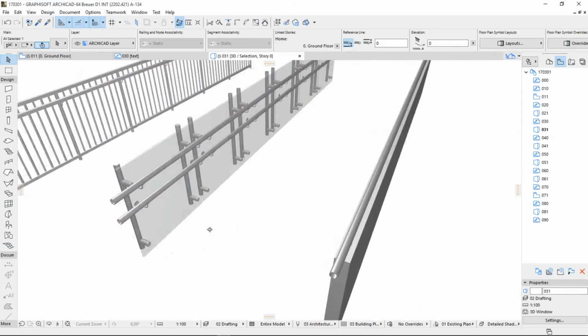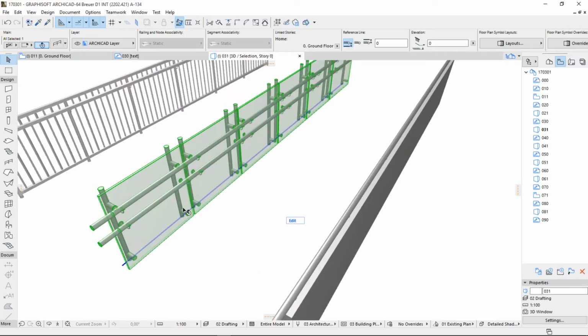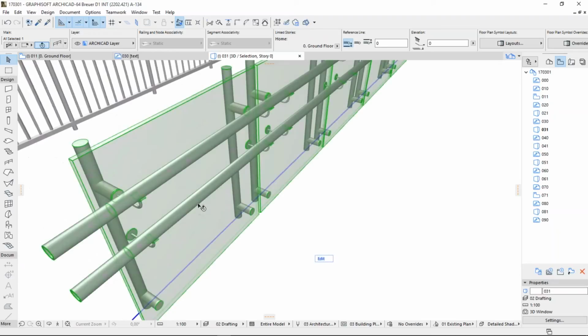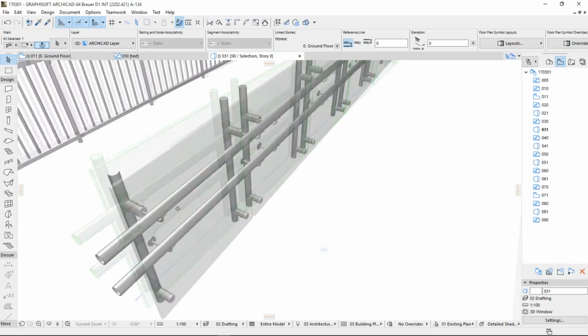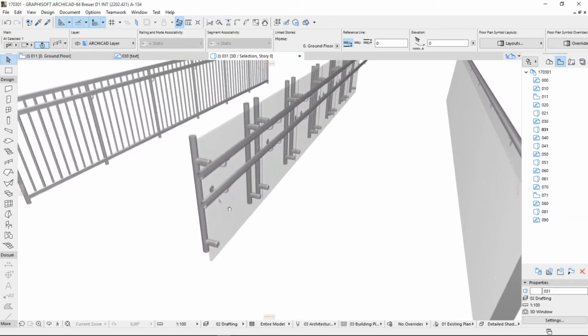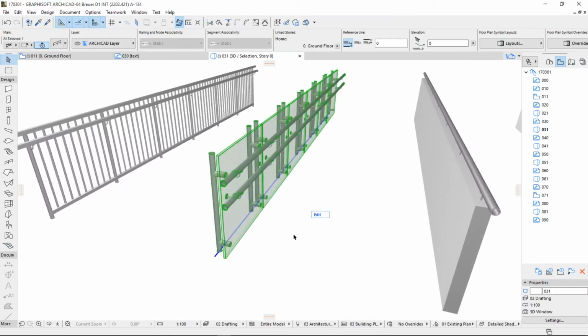Here is another one. This one has two inner posts, so they are actually twins next to each other. We have two handrails below each other, and we have fixings for each handrail. You can see the fixing here. This is the part that actually is holding the component. Now fixings can be specified for each element. So there's one type of fixing for each element. Of course, many types exist, but you can use only one at a time. And fixing is basically the subcomponent, and more or less the part of the GDL that actually holds the component. And you can have one at a time.